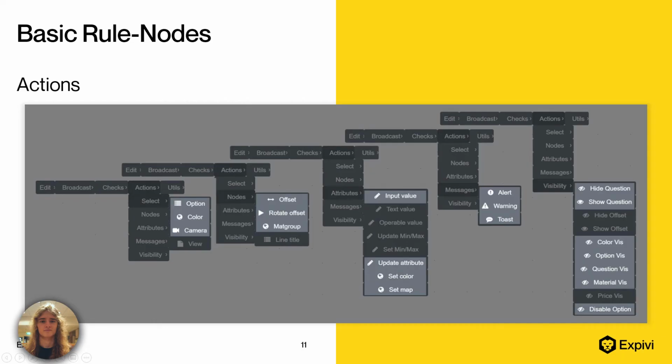The rotate offset node. This node allows the rotation of an offset group. The desired pivot point on the model should be moved to the origin 0.0.0 within the scene of your 3D file. The object should have its transform values frozen, reset, or locked, depending on the software you're using, and then translated back into the place where it belongs within the scene.